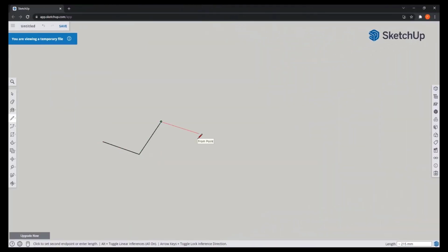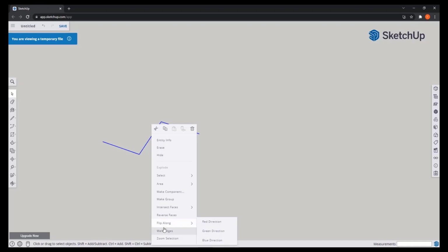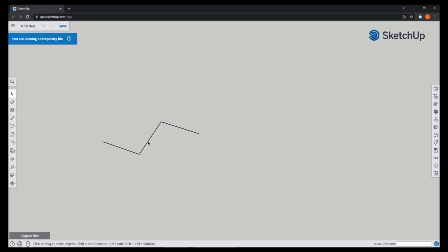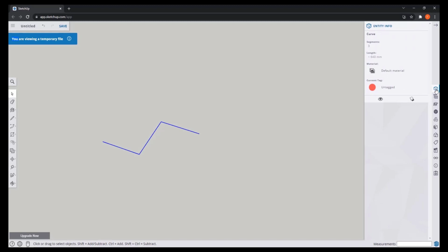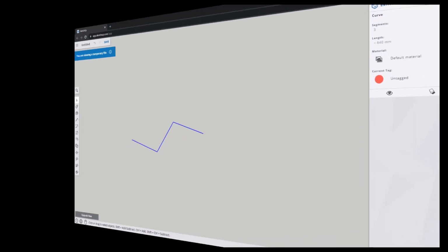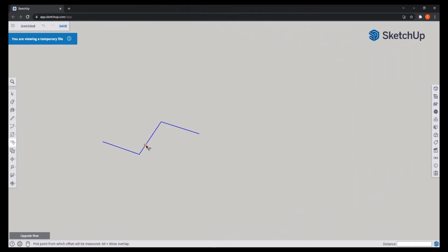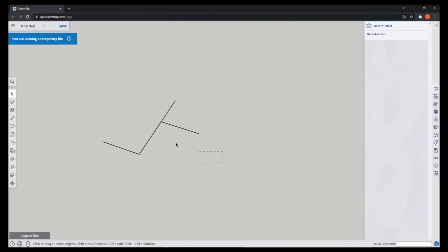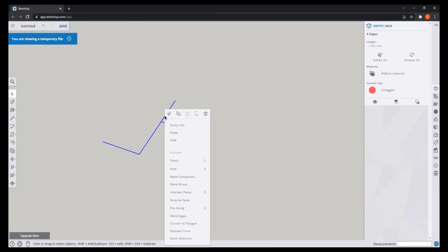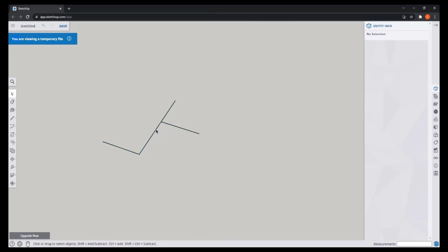And this also works to join connected lines with different directions. After applying Weld Edges, I convert them to a single object, and now this is considered a curve in SketchUp. Then I can apply, for example, Offset with just a single click to select the curve. Be aware, if I have an intersection of lines and I try to weld the edges, look that this only works until I reach that junction, and the other segments remain 2 separate lines.